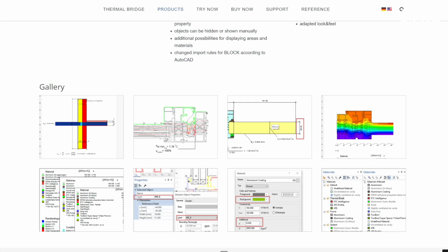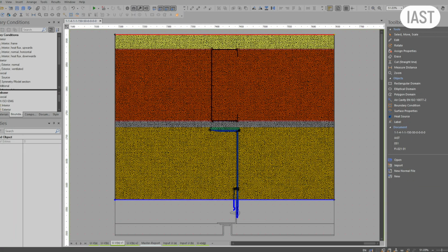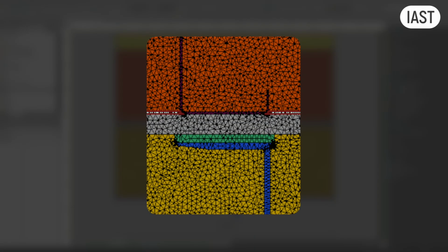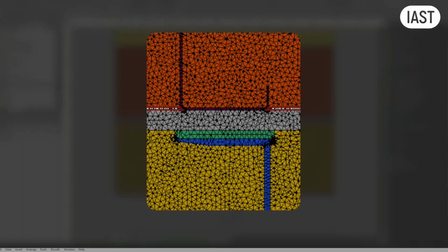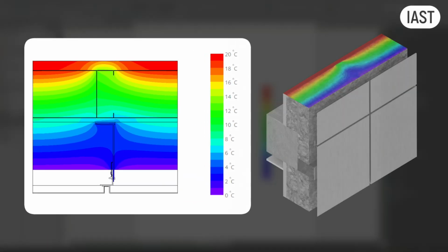Finally, level 4, finite element analysis. This is the desktop calculation that builds the correction database the level 3 tool relies on. The idea is straightforward. You take the entire wall, every stud, every bracket, every layer, and divide it into a fine grid of tiny cells and interfaces. Then the software solves the heat flow through each cell or the interface in 3 dimensions and pieces them all together. The output is a complete thermal map of the wall, heat finding its way through the brackets, through screws, along slab edges. It's the most accurate calculation available.